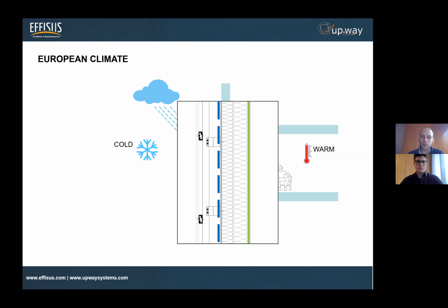Everything that we are trying to create here, providing dry insulation for the life of the building, could be compromised by that air leakage. And here, as we have a breathable membrane, we have the chance of evaporating any vapor that could be present within the facade.